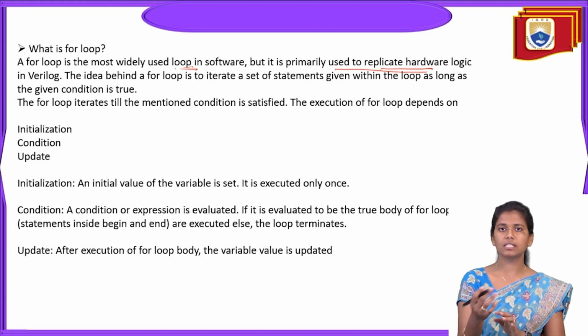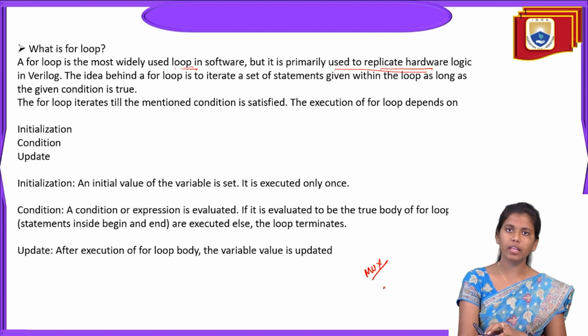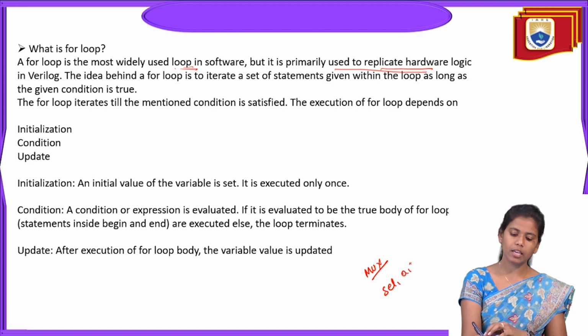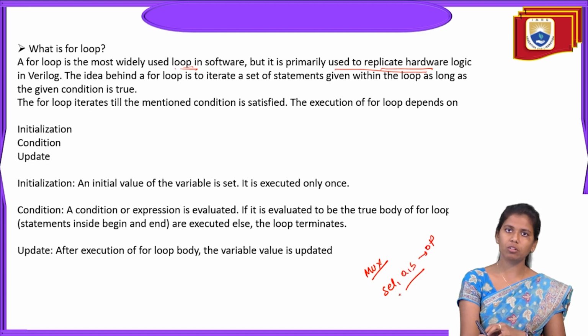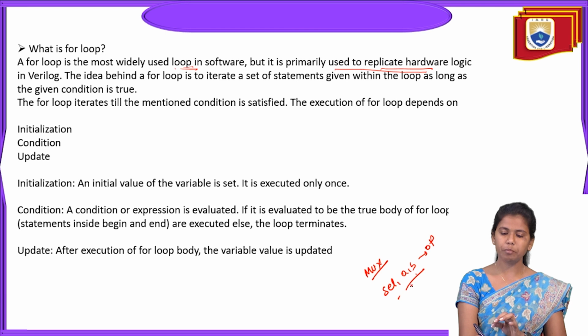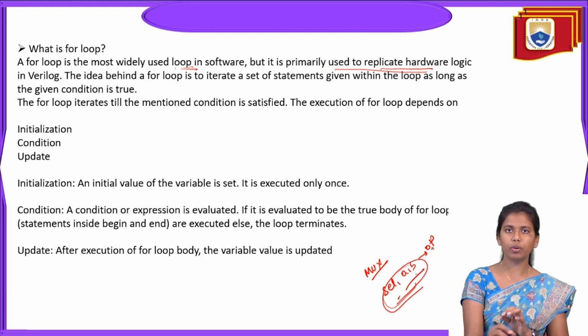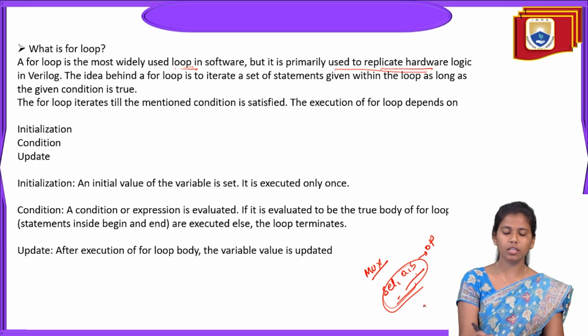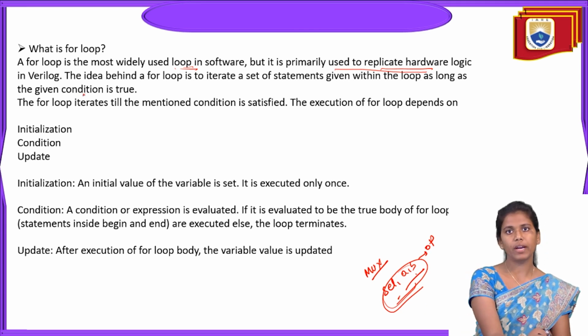Hardware logic is nothing but, for example, if you consider the mux. The output of the mux depends purely on the selection lines and the inputs, right? The output depends purely on the selection lines and inputs. So this is nothing but the hardware logic. Just to replicate the hardware logic, the for loop is most widely used.